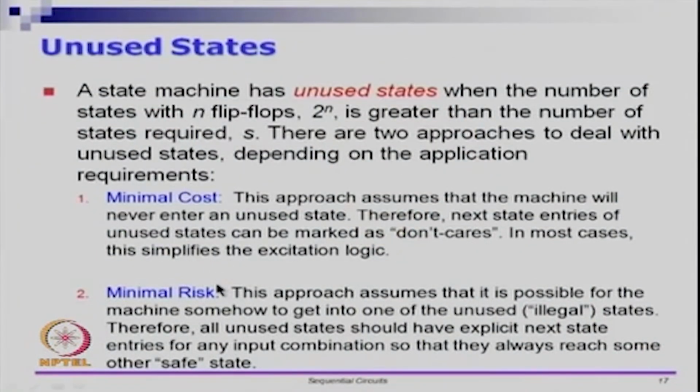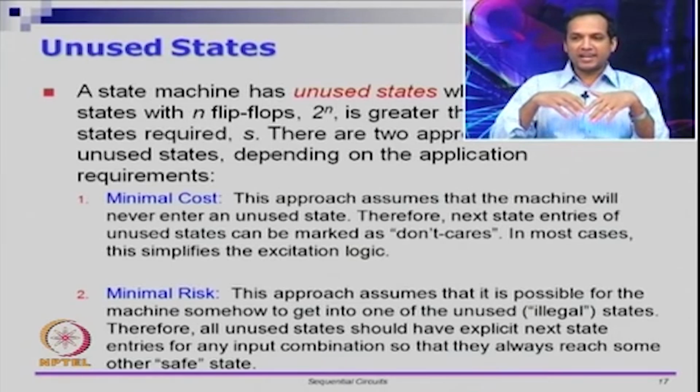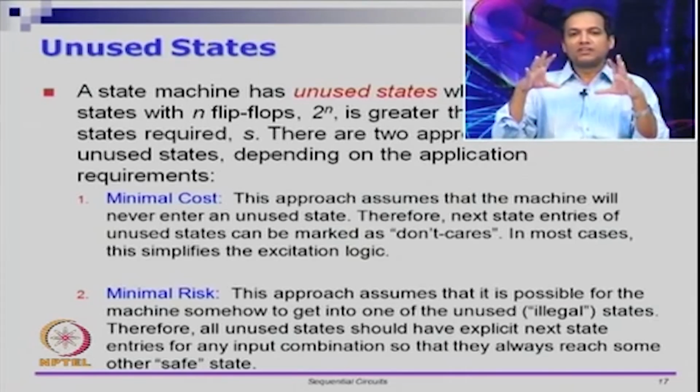Then there is this other approach called the minimal risk approach. Here, if by accident you somehow end up in the unused state, you put some state transitions there in such a way that you get to some known state. So both these things have issues.